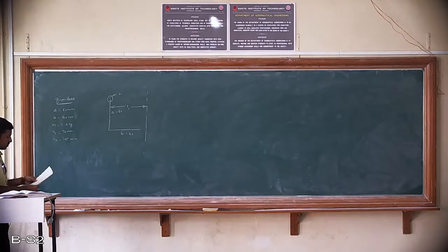The distance of the fulcrum of the bell crank lever is 75 mm from the axis of rotation of the governor. Let us see what that 75 mm is afterwards. The minimum equilibrium speed is 420 rpm and the maximum equilibrium speed is 4% higher than this value.